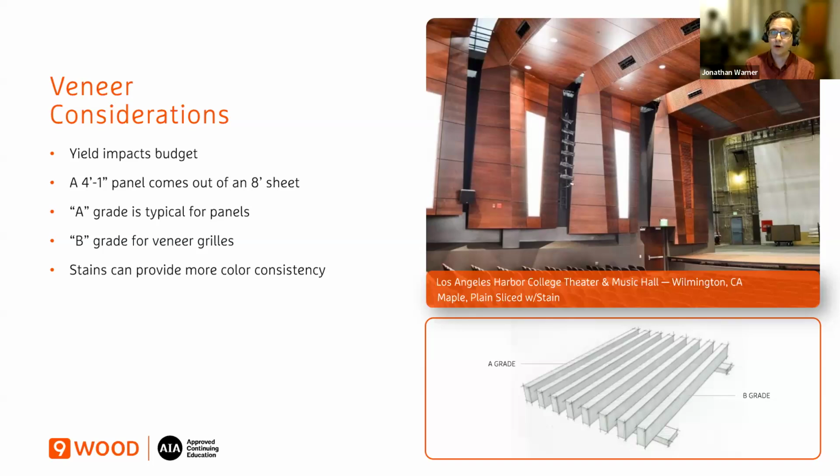And so it's going to be more expensive than if you stay on modules. Ideally, a 2-foot, 4-foot, and 8-foot would be the best yield, so it's something to be aware of. If you don't particularly need the 4-foot 1-inch panel, having a 3-foot 11-inch panel would produce a lot better yield. You can get 2 of them per sheet.